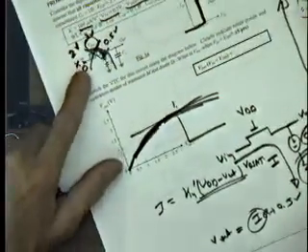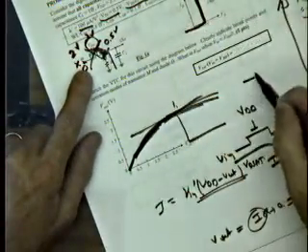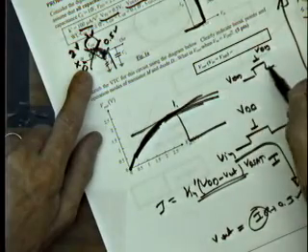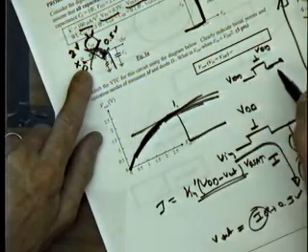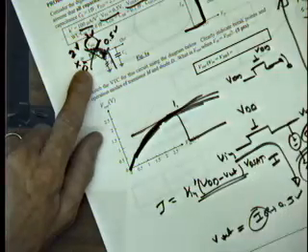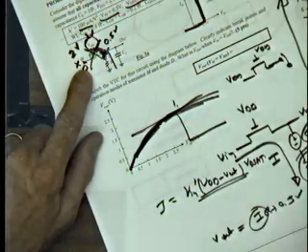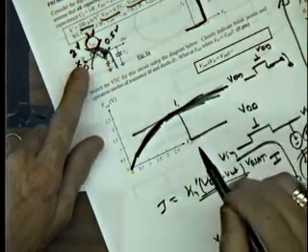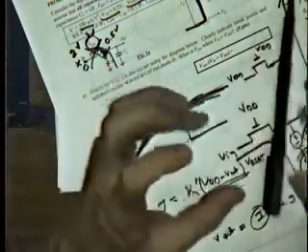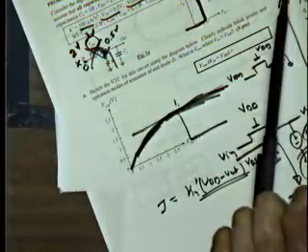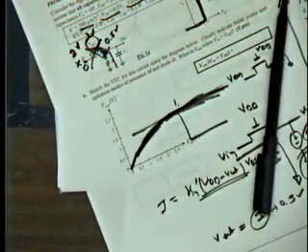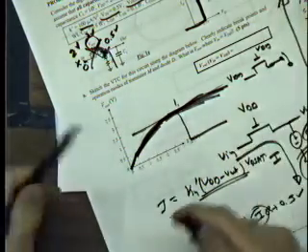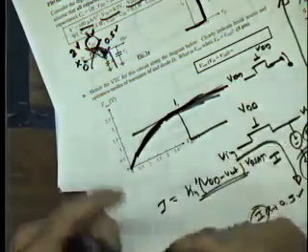But no, actually it cannot. If this device is at VDD, and this is at VDD, from the time this node goes a little bit below VGS minus VT, the transistor turns back on. So it's going to keep it at 1.5 volts. It's going to clamp it, like something that clamps this thing all the way to 1.5 volt. You pull it a little bit lower than that, it's going to pull it back up. So it is staying at 1.5 volts. Okay? But it's an interesting thought process.